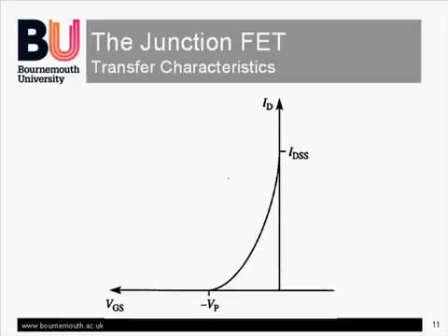At the one extreme of this rather nonlinear square law characteristic, the gate voltage provides sufficient reverse bias to cause pinch-off at -Vp when there is no drain current, that is, without any help from the potential gradient in the channel. At the other extreme, with zero gate voltage, it's the channel potential which causes pinch-off. The drain current is then at its maximum possible, or saturation drain current, IDSS. These two parameters are important in characterizing the JFET performance.